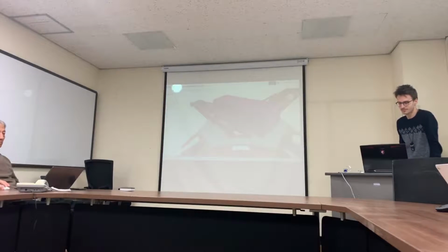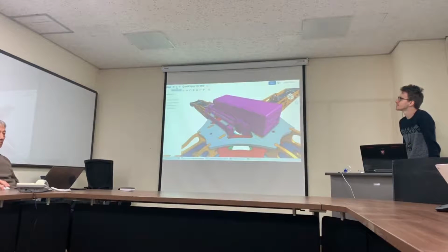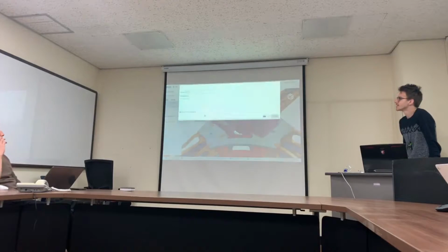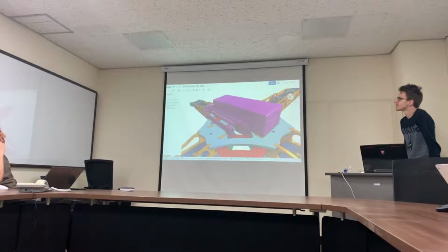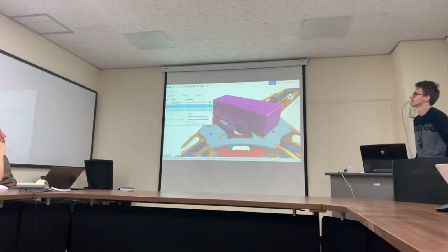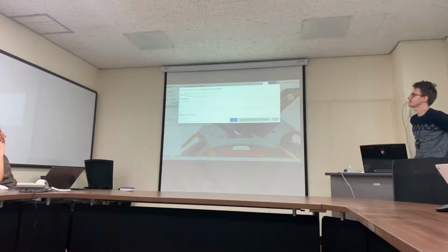From the version manager, you can create branches from any named state, forking the design at that point and enabling parallel independent development efforts. Here we are creating two branches, one arbitrarily for assembly changes and the other for geometry development.